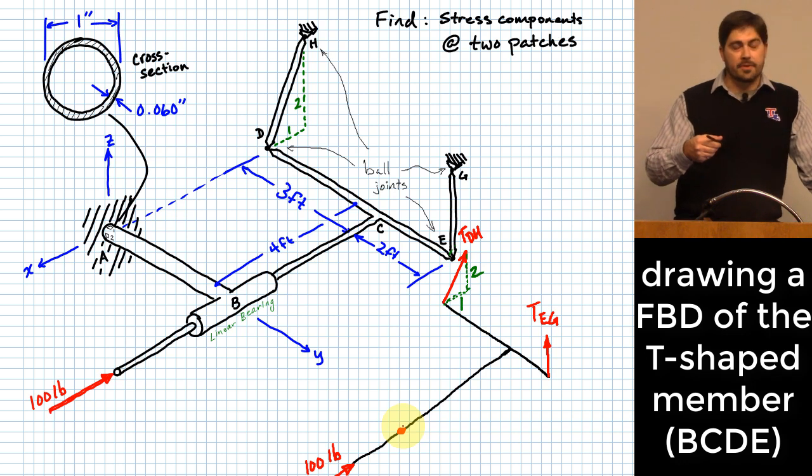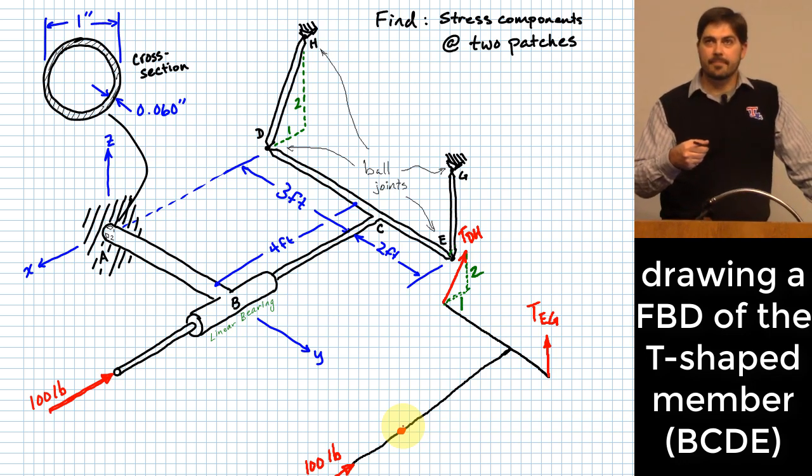And what else do you think? Okay, rotation around the x-axis, right? So it can slide along the x-axis, and it will be free to rotate around the x-axis. So those are the directions we will not have reactions. The other directions where it constrains movement, that is where we will potentially have reactions. So that would be what directions?